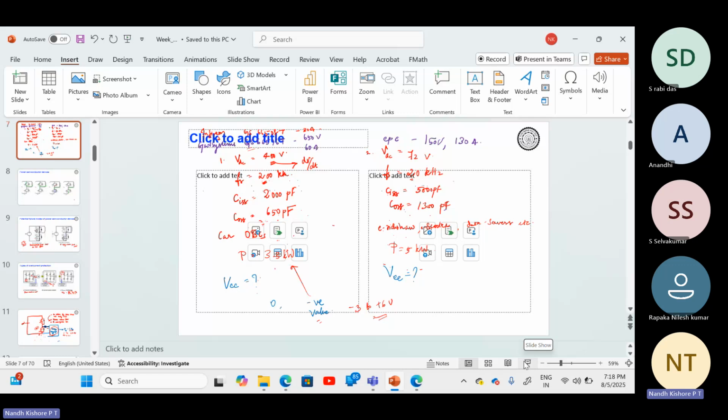But for typical 800 volt applications or even higher, you still have to rely on SiC devices or IGBTs and so on. But GaN devices are a very good option for low voltage applications. Even your Apple chargers, Samsung chargers, and laptop chargers, most of them have started adopting GaN devices, and that enables the fast charging that you are seeing nowadays.